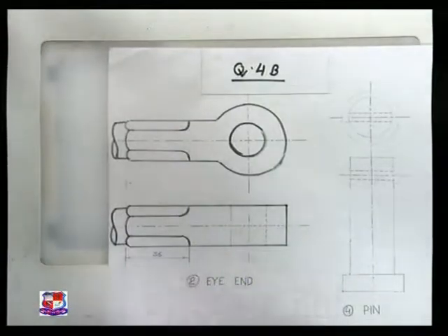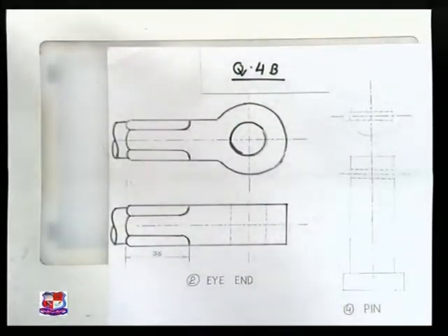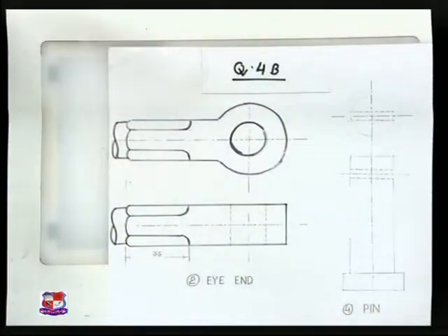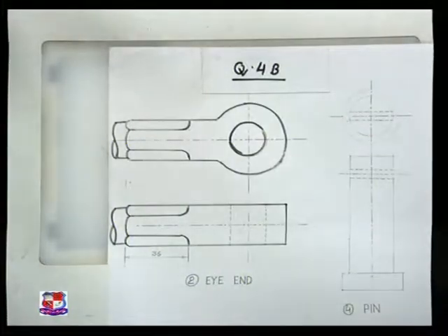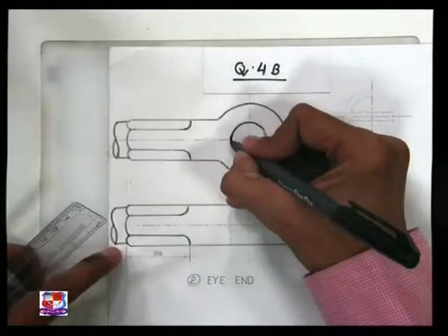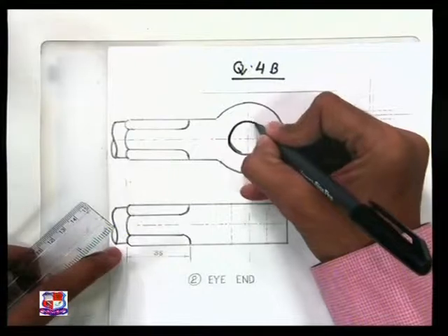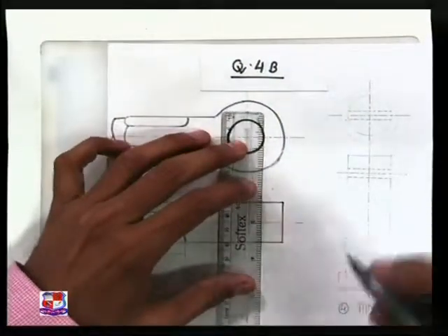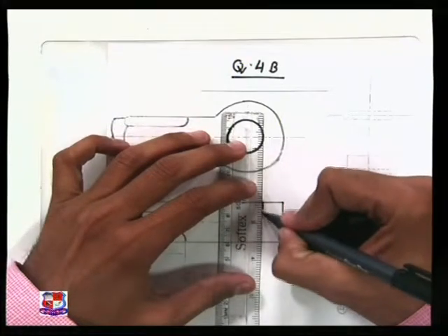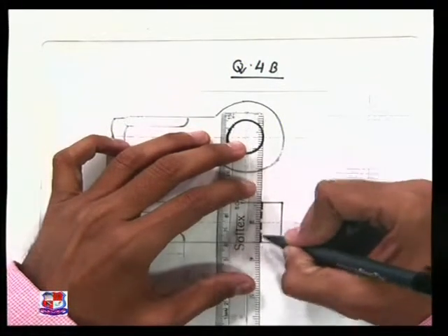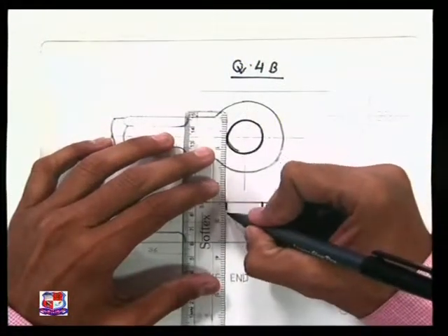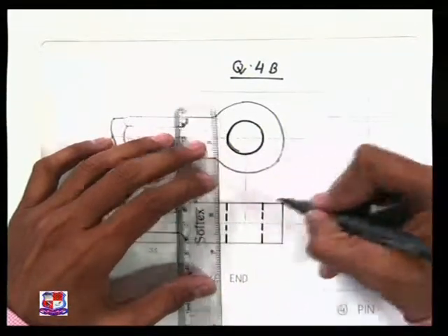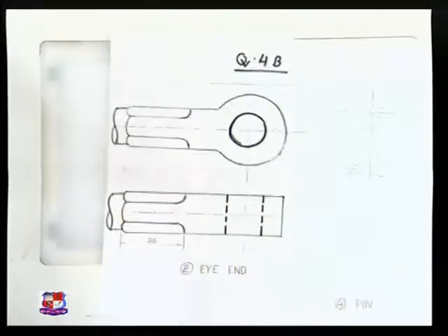So this is the top view, this is the front view. Now in the front view, one parameter is missing, this drilled hole. This hole would not be directly visible in the front view, hence to mention this invisibility of that hole we use a dotted line like this. This dotted line shows that it's a circular hole.